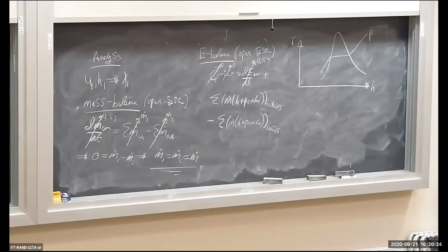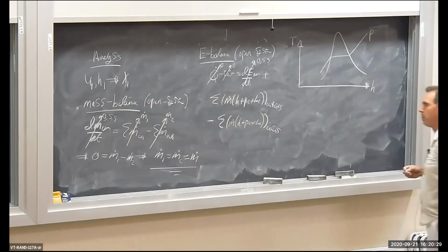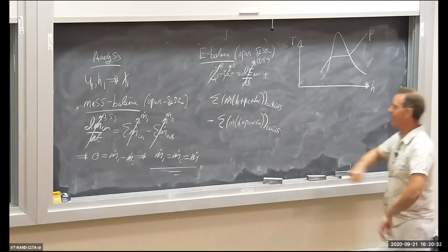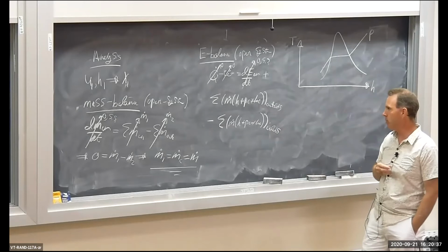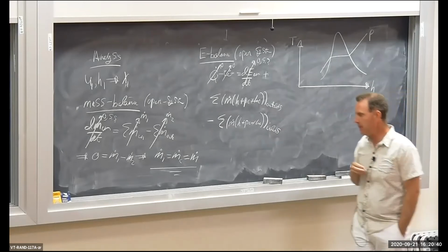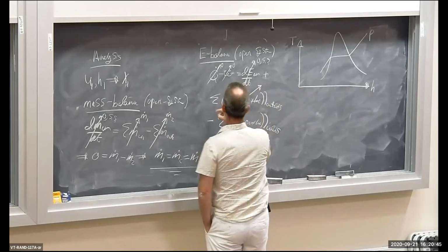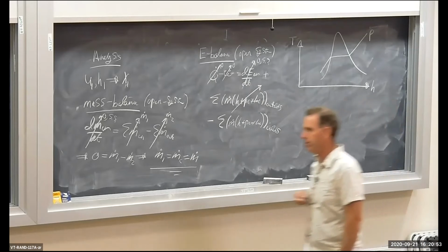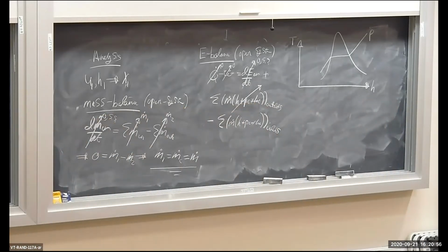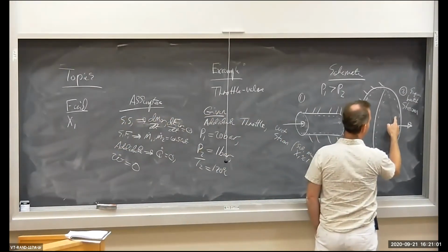What other terms can we look at? What else can we maybe get rid of in the energy balance? What about the specific kinetic and potential energy terms at the inlet? We need to work on these mass flow terms. Let's work on the outlet term: the sum of m dot times h plus PE plus KE, summed over all outlets. How many outlets do we have? As you can see in the diagram, we have one outlet, at location 2.